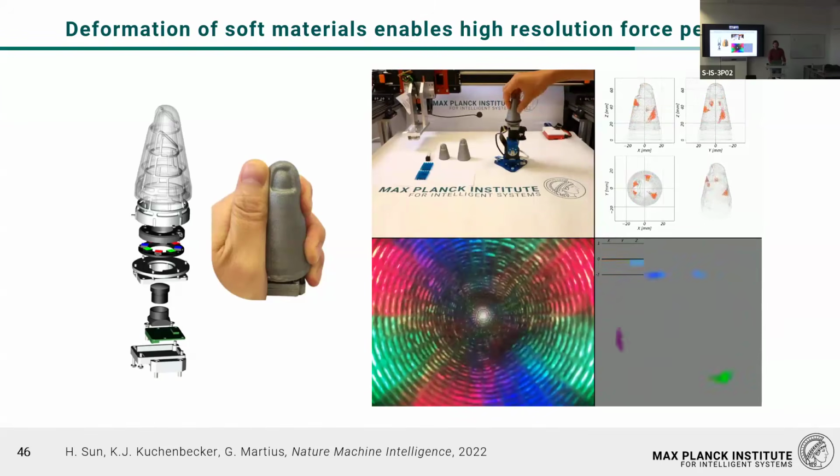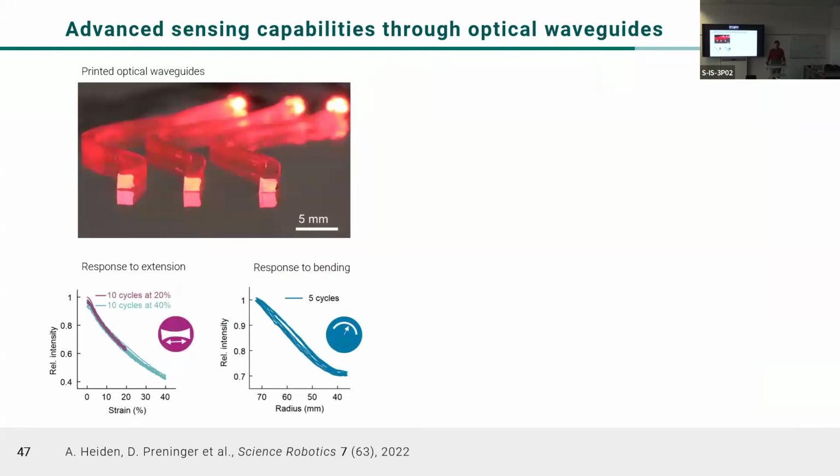To measure deformability, we could also use something that actually measures stretch and deformation. And here again, an example where we use light to do that. You can think of building an optical waveguide, the same technology that we use to get internet at home, but from a deformable, stretchable material. And then use physics to build a sensor. In a waveguide, the loss of the light intensity depends on the length of the waveguide. And if we start stretching it, the intensity will drop.